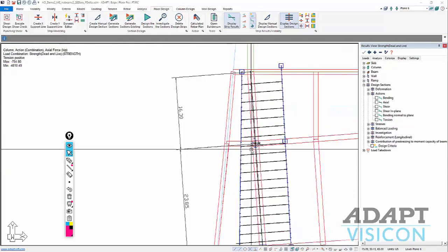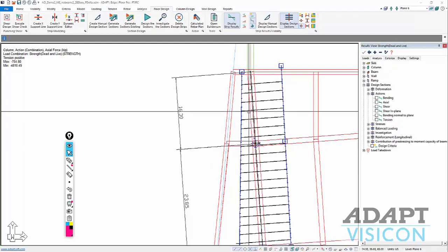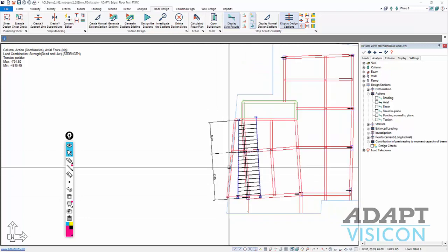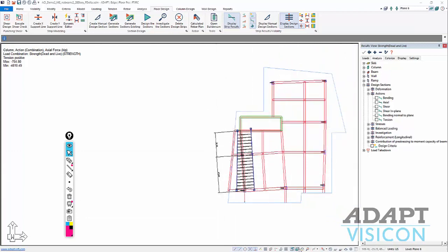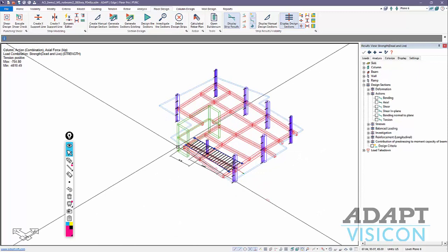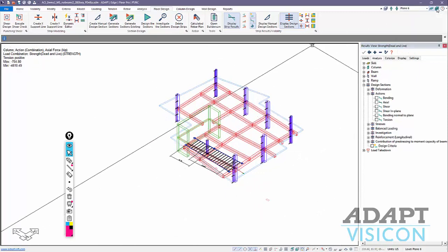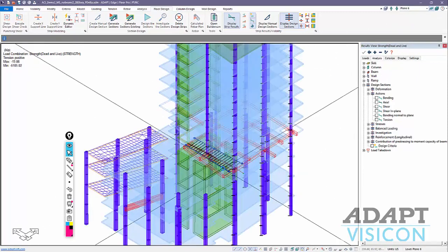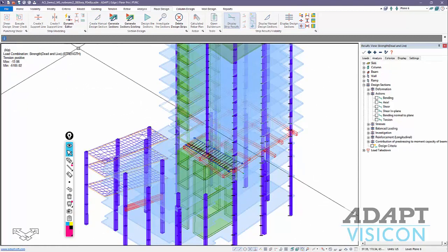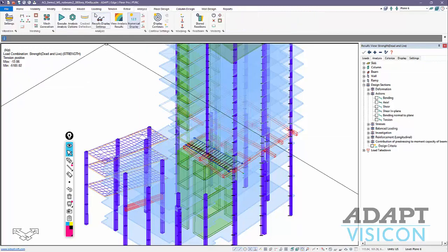So because we've entered a new component, which is post-tensioning, we actually need to reanalyze the structure. Otherwise, we don't get an updated solution for the hyperstatic actions from the PT. So this will require us to come back. Because we're first illustrating the direct method using global FEM results, we're going to go right back to global analysis. We now have some post-tensioning there, and we're going to analyze the structure again.